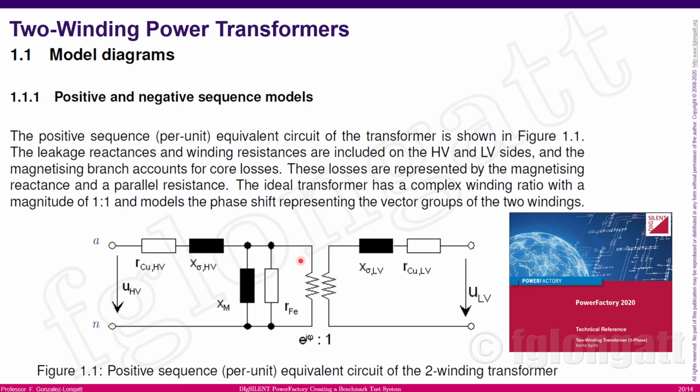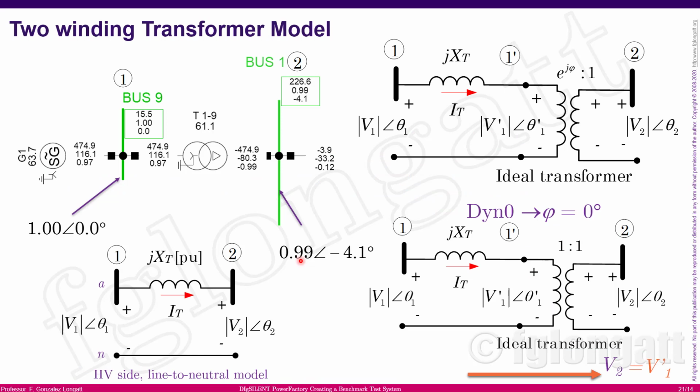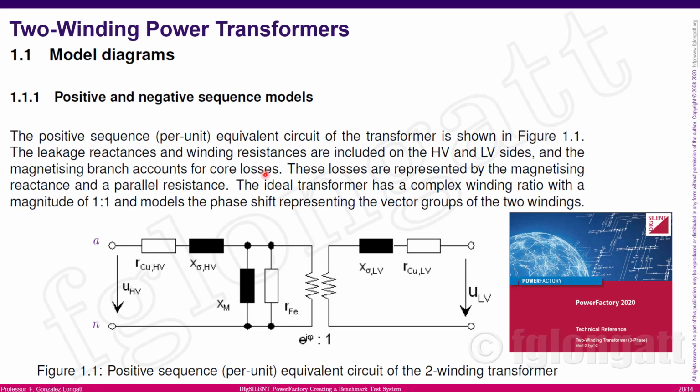And now what I will do is use those concepts to show you with numerical values. And it's extremely simple, okay? Let me come back here. If we assume that this transformer has no losses related to the core, we can remove this branch, okay? Then we have the series impedance on the high voltage side and the series impedance on the low voltage side. We can move this impedance to one of the sides. It's okay, we can do that. The other thing that we can assume is that there are no copper losses in the windings, and as a consequence, those resistors will disappear.